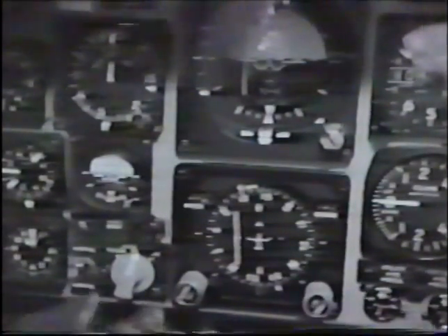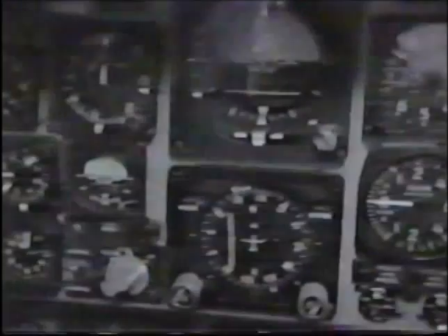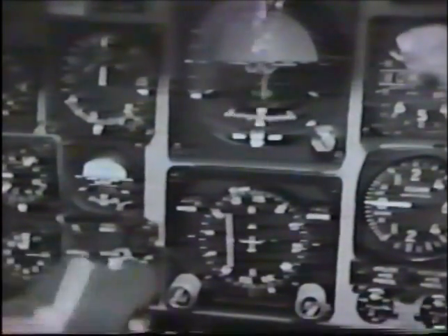Also, if you are within range of the ILS glide slope signal, you will see the glide slope indicator in view on the ADI. Now select ILS and look for the pitch and bank steering bars on the ADI. The ILS is now checked, so go back to TACAN.